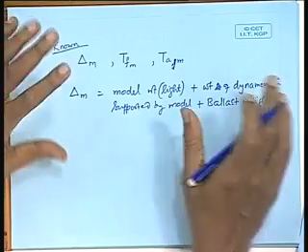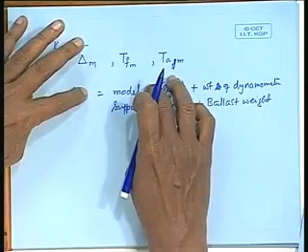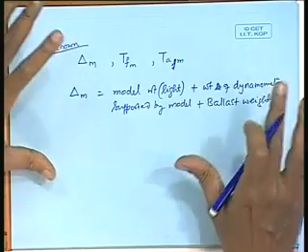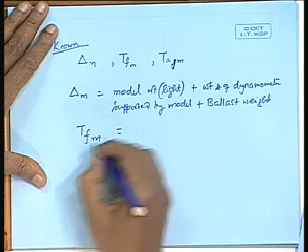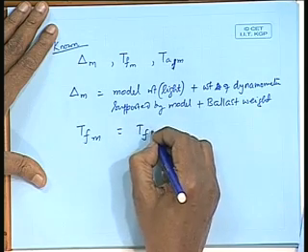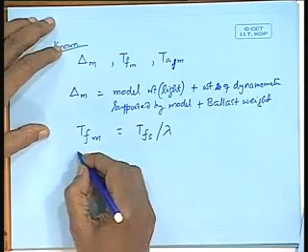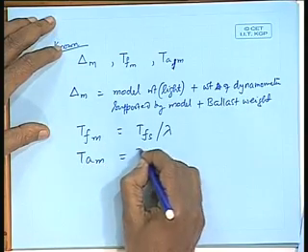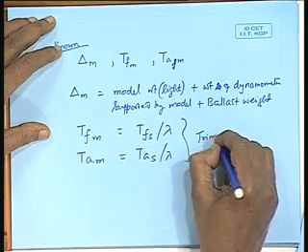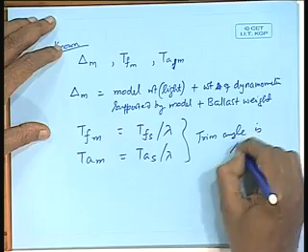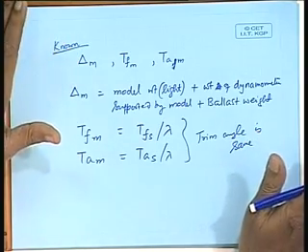Okay. So, you have to calculate how much ballast weight will go, and then the model has to be weighed, and you can get the model displacement similarity. What is draft aft and draft forward? That is ship draft divided by lambda, geometric similarity, and similarly draft aft. The trim angle is the same, the angle will be same. So, the model has to be prepared.